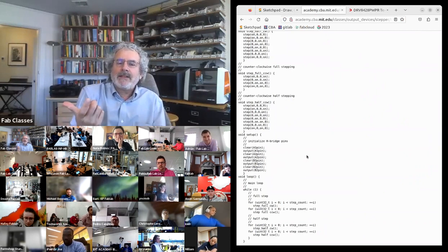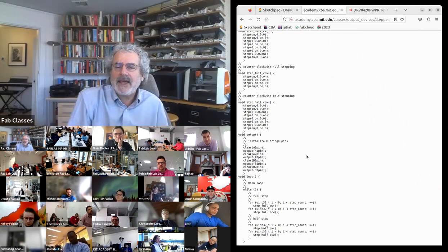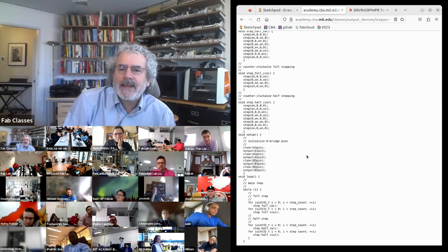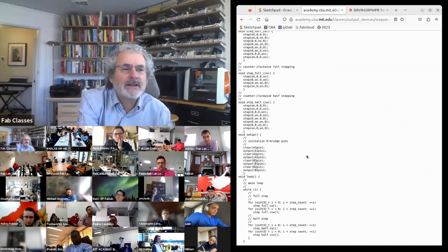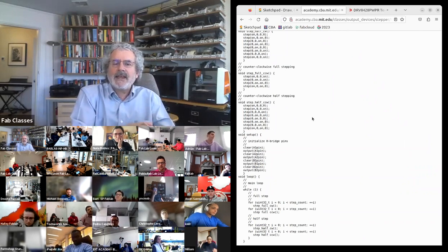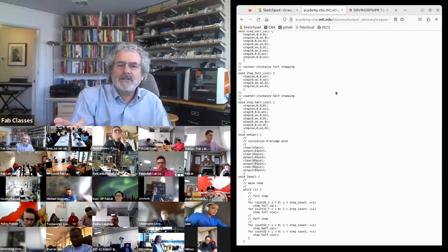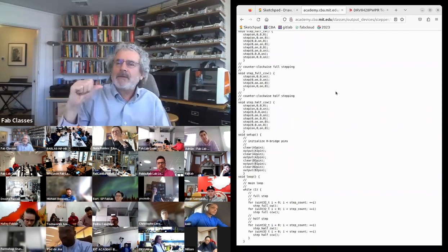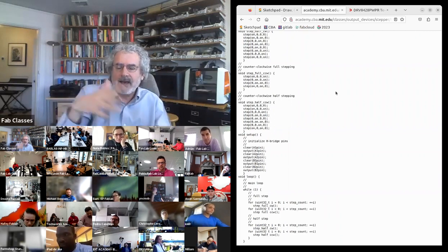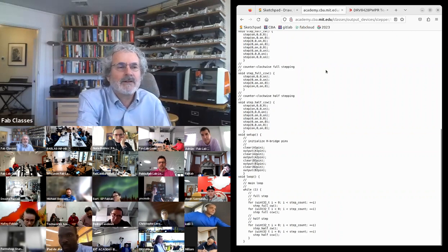And so this doesn't depend on a particular motor control chip. It just is an H bridge, and those are pretty generic. And then in software, I can figure out how to control it. And so we've gone back and forth between using these dedicated chips and just doing software stepping. Yeah, Stephen is noting microstepping is reducing torque compared to having just the current full on the magnet.